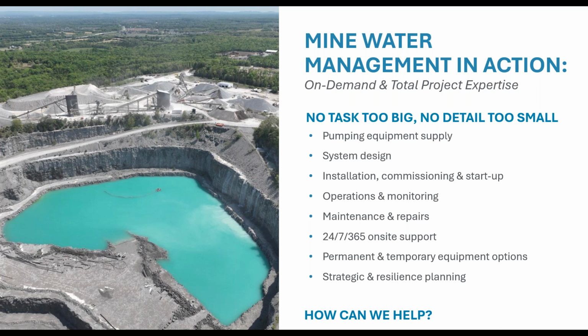Obviously, we would recommend cleaning out the sump to remove any built-up sedimentation, and look for ways to reduce sediment buildup in the future with either a settling tank or additional screening.